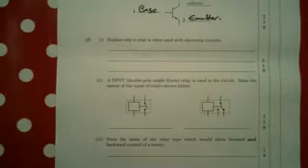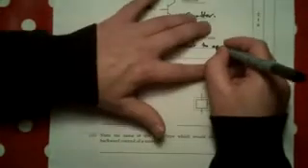And it says, here's the symbol for the transistor. We've got the base and the emitter. Explain why relay is often used with electronic circuits. Well, the control side of the circuit is usually quite low powered, maybe 5 volts. So it allows a 5 volt control circuit to activate 240 or mains volt load circuit.